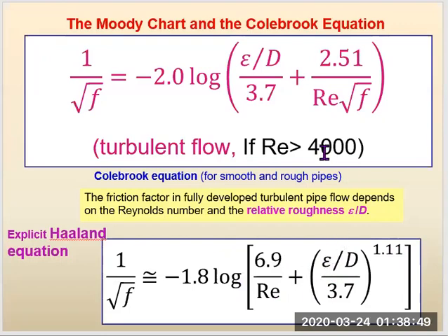The epsilon is the roughness of the pipe surface or the channel surface or the duct surface. This is the roughness and has a length scale, so it is in meter or millimeter or centimeter. You need to read that based on the type of the duct from the appendix, or sometimes it is given in the problem statement.